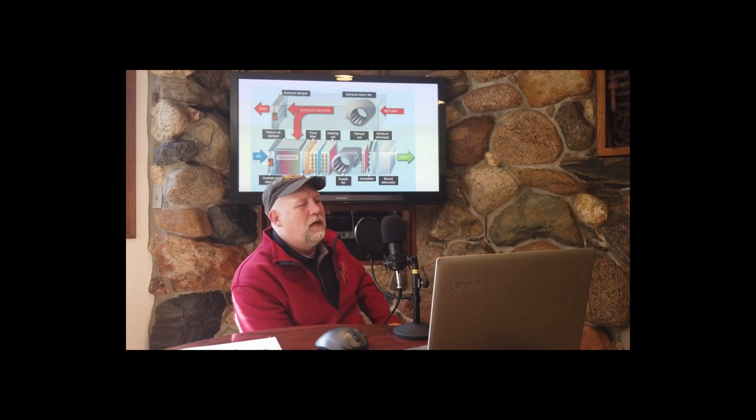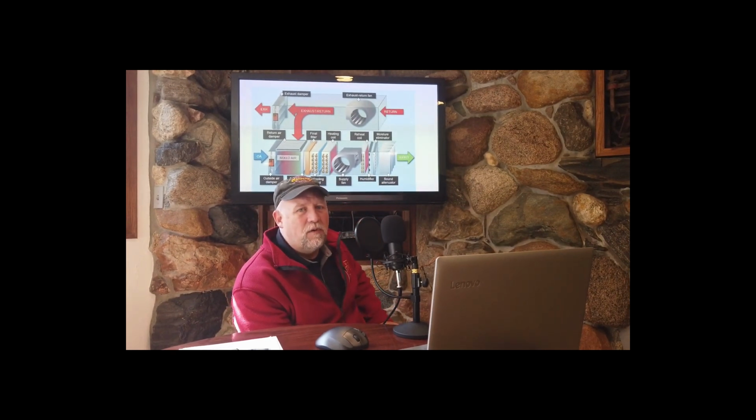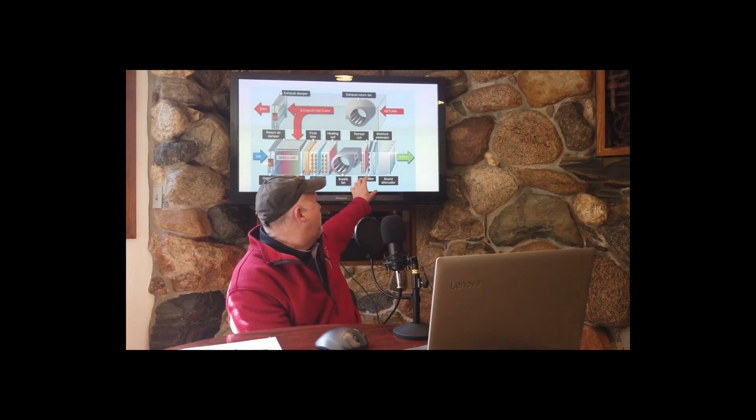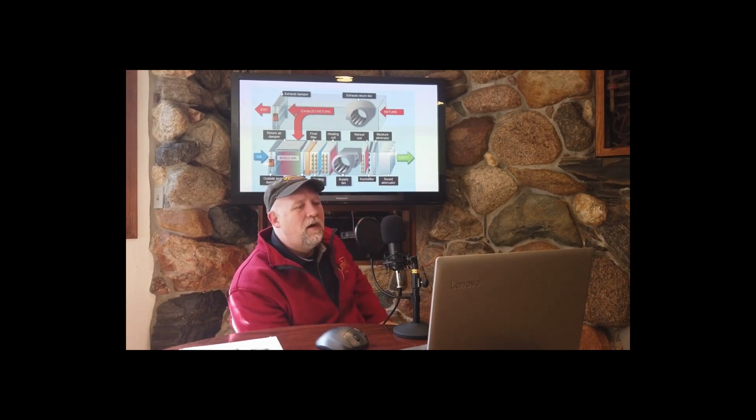Most buildings will not have a humidifier section on them. Even older buildings that were built with one, most of them have been disabled just because of the problems humidifiers can cause in a building. So just know, the humidifier section, very optional. Sound attenuator, also very optional.